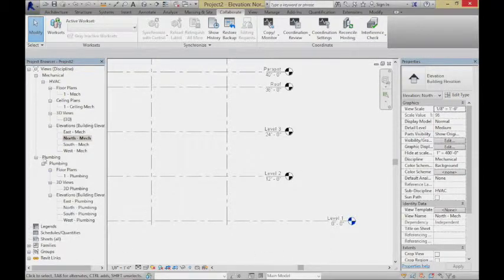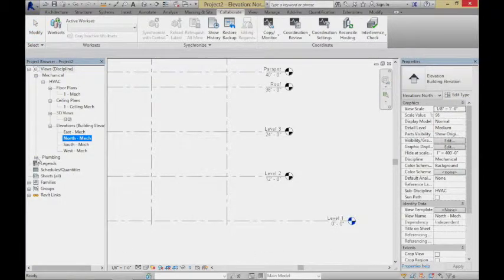I have a choice now. I'm going to put some registers. Okay, I'm going to put them above my head. In terms of doing that, I can think about putting them on the floor plan. Let's say I'm going to put some registers on the second level. I'm going to put some ductwork in the second level of the building between 2 and 3 up in that space. I could try to put them in the level 3 floor plan and look down through the floor. It'd probably make more sense for me to put them on the level 2 ceiling plan and look up.